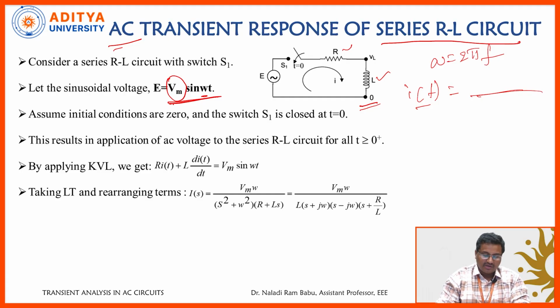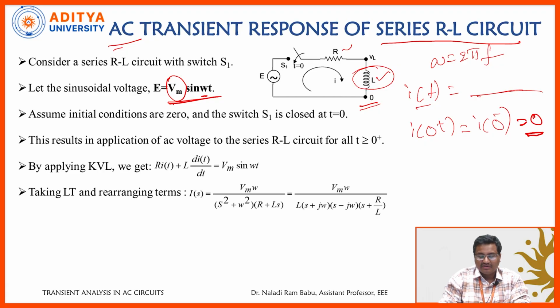Before starting, here we have an inductor, and an inductor does not allow a sudden change in current. Therefore, the initial value condition will be I of 0 plus is equal to I of 0 minus is equal to 0. The reason is the inductor does not allow any sudden change in current, so this will be the initial value condition.